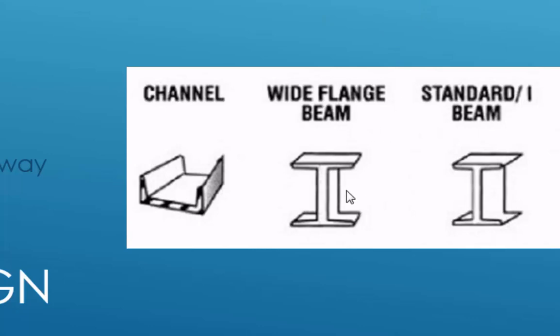And also, if you are building a structure that has supports that are coming off the insides, if you will, of this W shape, then it is supported in the middle. So you'd really start to consider the other direction, the strong direction, as where it's going to buckle, because the weak direction is supported.